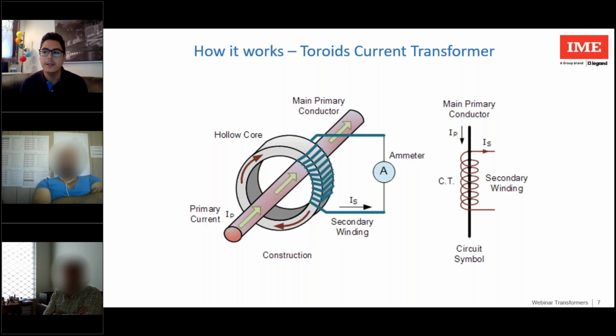Coils capture this current flow generated by the magnetic field and return it on the secondary side at a current value proportional to the flow of the primary. This ratio, as I said, is given by the number of windings made on the transformer core. Does anything change for the primary winding type? Well, mostly nothing.